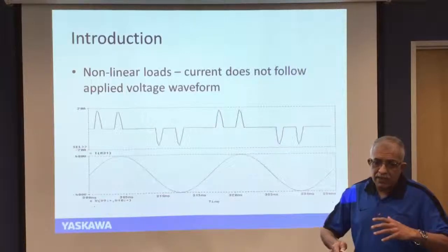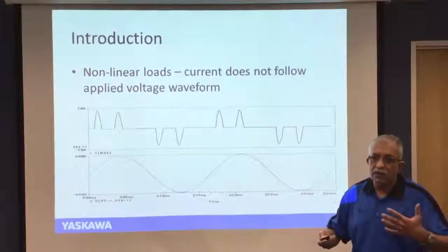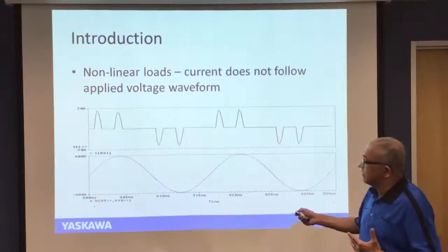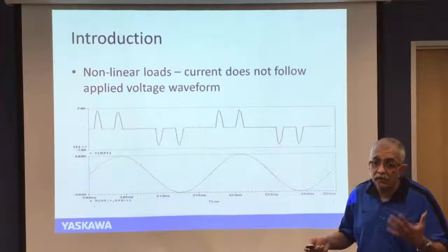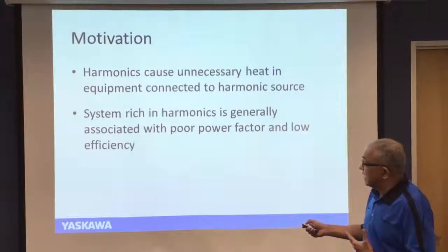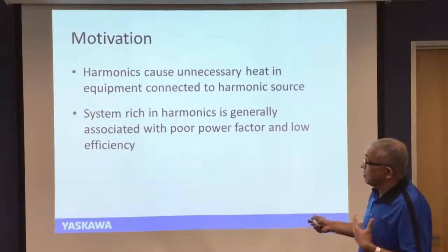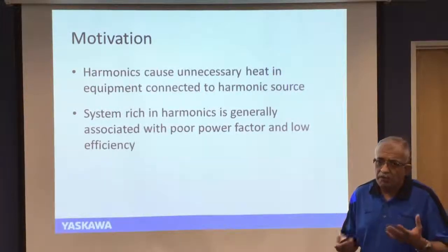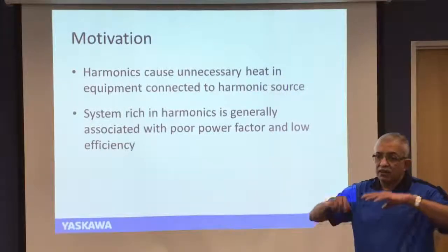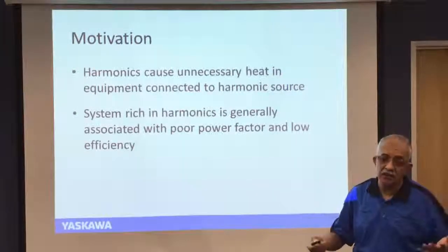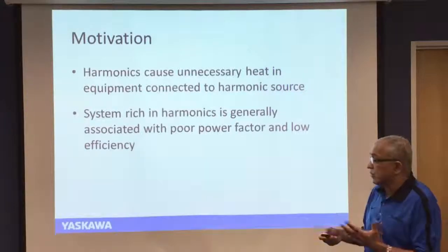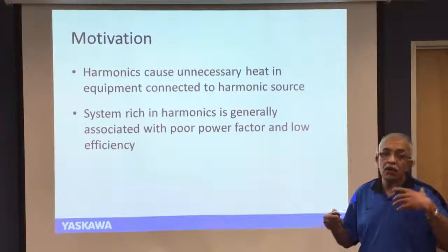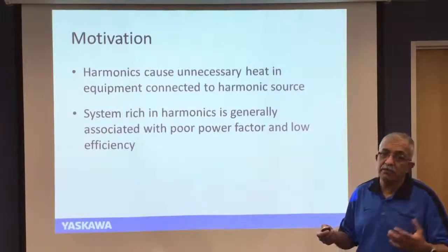So in other words, the reactive VARs or the useless current which we have to carry to recreate this kind of waveform is a stress, a burden on the power system. A system rich in harmonics is generally associated with poor power factor and low efficiency. Poor power factor means the reactive VARs in the system are much higher than what we actually need. And those are the two main motivating factors why we have to deal with non-linearities in a given power system.